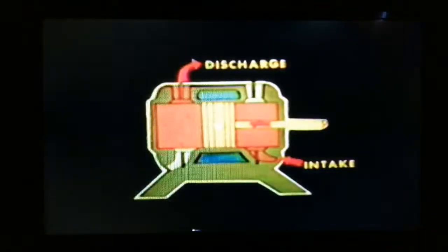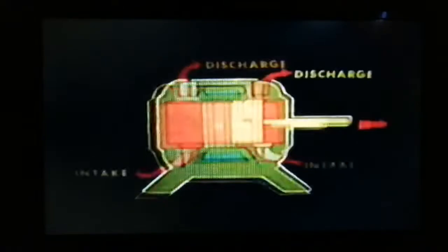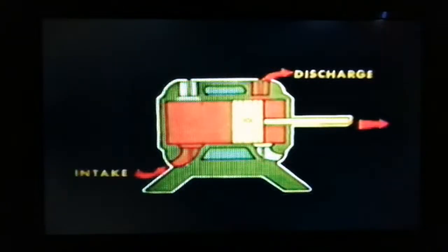Usually the unit is designed with pairs of air cylinders so that one discharges its pressurized air, the other is drawing in air. This is called a double-acting cylinder. As the piston travel reverses, the newly filled chamber becomes compressed and its air discharges into the system. To carry away the heat of compression, cooling water will usually be piped through the jackets of these rugged workhorse compressors, and should the cooling water fail, internal heat may cause damage to the unit.